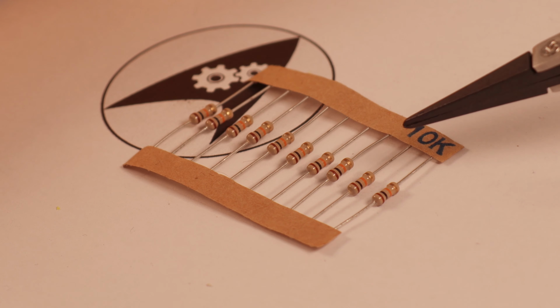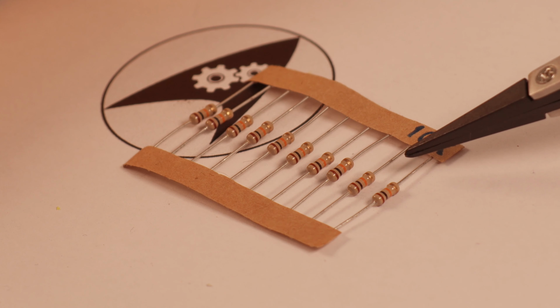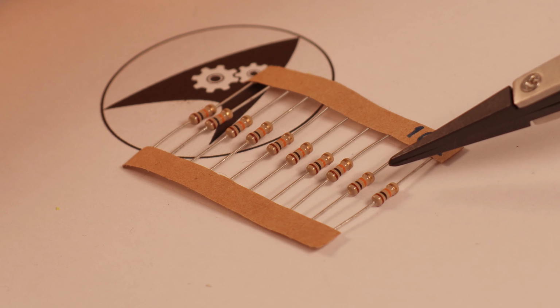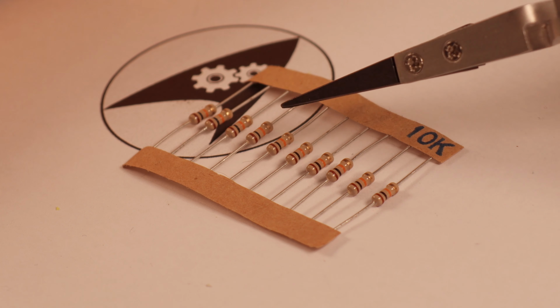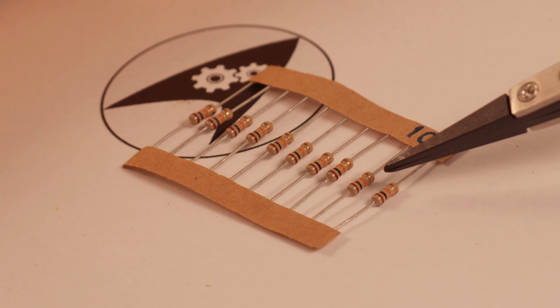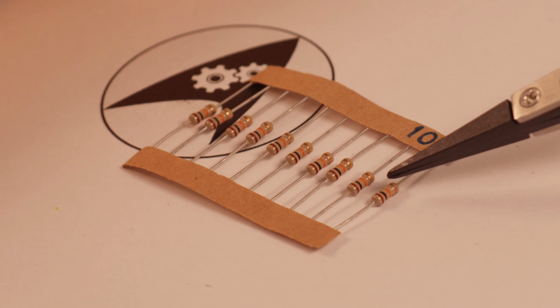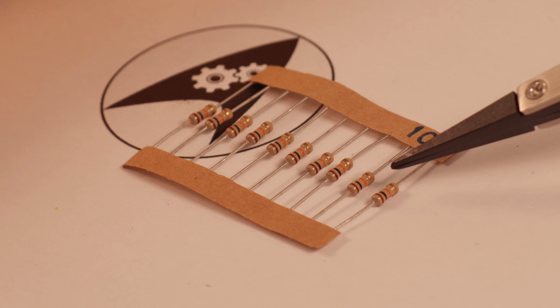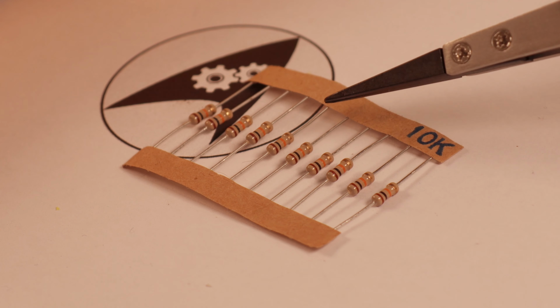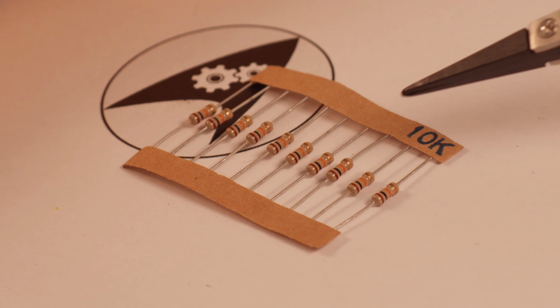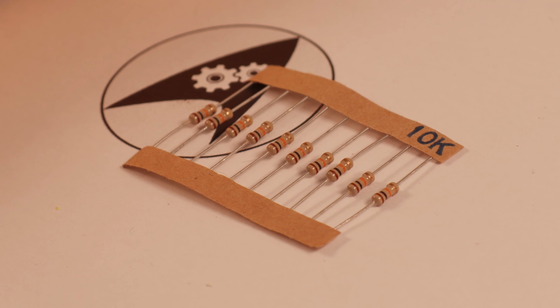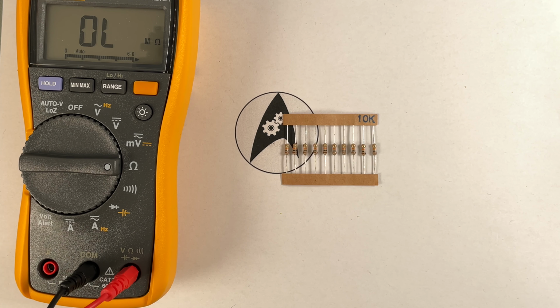And before we observe Ohm's law in action, let's actually measure the resistance of one of these resistors, because there are going to be some differences between these. Even though they look all similar, we have one of these colored rings which gives us the tolerance of the resistor, and the tolerance says that not all the resistance values are going to be similar, but there are going to be deviations. And we want to know exactly what resistance value is behind the resistor we're going to use for our experiments. So in order to do so, let's switch the multimeter on the left side to ohms.